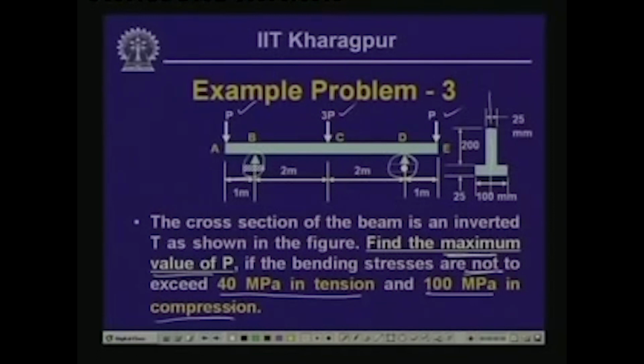In the previous 2 occasions, where we dealt with a rectangular or a circular cross section, both sections were symmetrical with respect to both the vertical and the horizontal axis, and we did not bother about the limits for compressive and tensile stresses, because the magnitude of the stresses developed because of a bending moment at any section would be the same, since the values of I and y are the same at the extreme points.